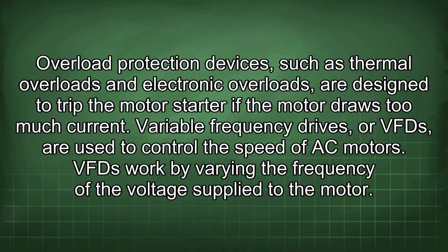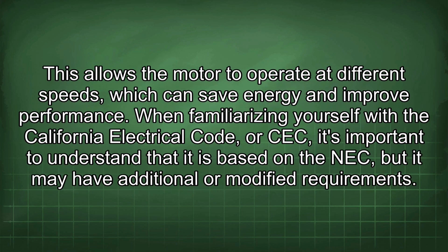draws too much current. Variable frequency drives, or VFDs, are used to control the speed of AC motors. VFDs work by varying the frequency of the voltage supplied to the motor. This allows the motor to operate at different speeds, which can save energy and improve performance.